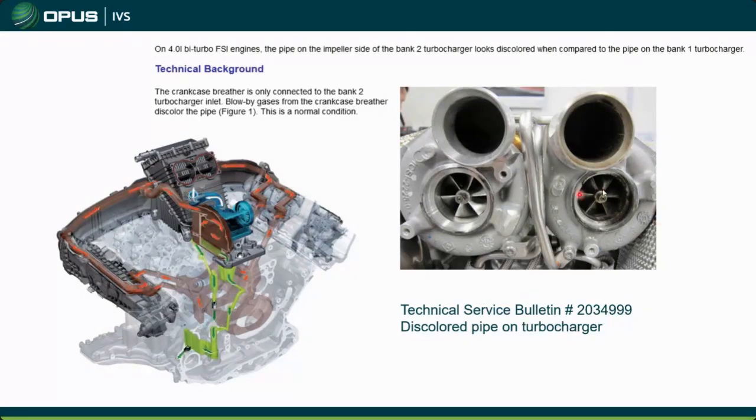Obviously, all your blow-by gases are shooting through this turbo. Now, personally, I don't like that, because what you're doing is you're shooting oil and blow-by gases onto a nice hot turbo. I mean, of course, it's going to discolor it. You're going to get some carbonization. You're going to get some buildup here, and then meanwhile, you've got a nice shiny, perfect turbo over here. So a little bit of a weird design, but it is what it is. That's what they do.